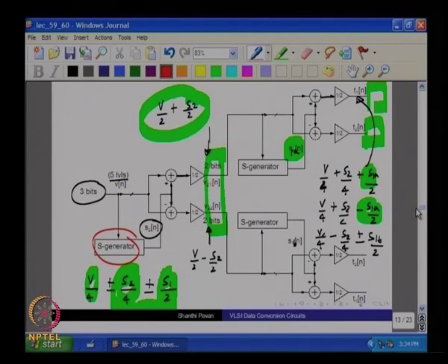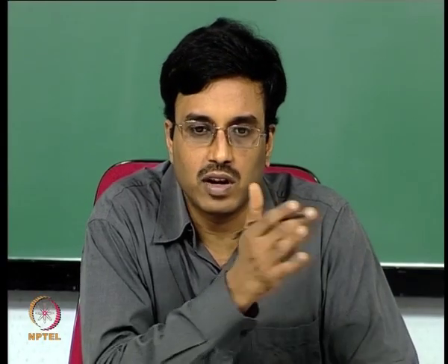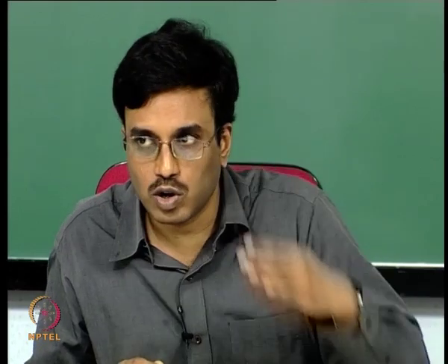Historically, of course, people thought completely differently, and that line of thought gives rise to a whole bunch of mismatch noise shaped architectures, where the benefits due to mismatch noise shaping are not as evident as they are here, right. Here we knew what we were doing, we implemented exactly that, and the fact that we should expect mismatch noise shaping, the fact that we should expect first order residual noise is all very apparent, right.